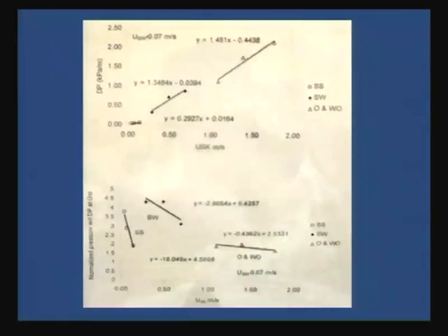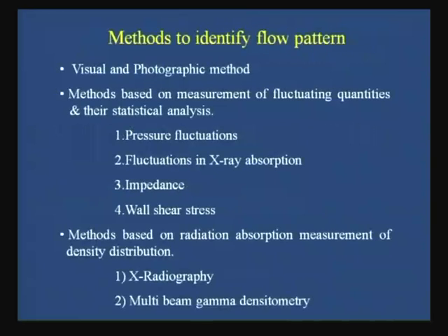Initially we had discussed the different techniques to measure the pressure drop, and we found out that we do that for any particular fluid flow problem, be it a single phase flow or a two phase flow or whatever it is. But what are the extra challenges in measuring pressure drop in two phase flow situations? This was number one. After that, the next thing, the estimation of void fraction, which you do not need in single phase flow. It is a unique parameter which you need to know for any analysis of two phase flow or multi phase flow situations.